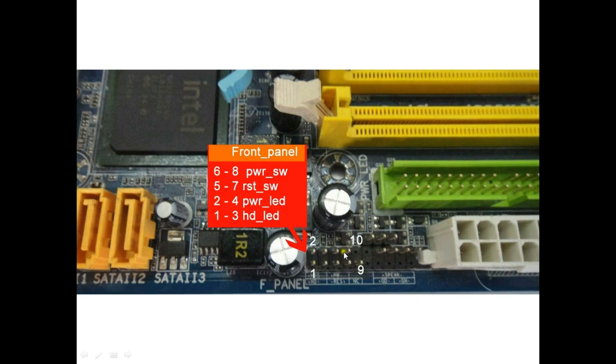The two pins which are adjacent to the 10th pin will be the power switch pins. We connect the power switch here, and opposite to the power switch we connect a reset switch, pins 5 and 7. Adjacent to the power switch we connect a power LED, that is 2 and 4, and opposite to the power LED we connect an HD LED to these two pins, that is 1 and 3.